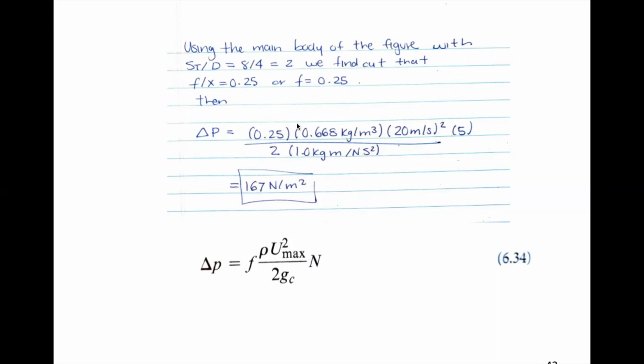So again, what you need to solve for this is just this F, the friction coefficient that you get from the figure. Be careful when solving problems for tube banks. We have a figure for staggered and we have a figure for inline. So as you can see, solving for a tube bank requires a lot of tables, a lot of time.